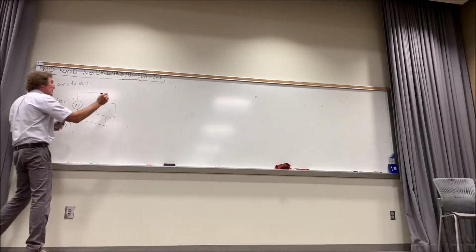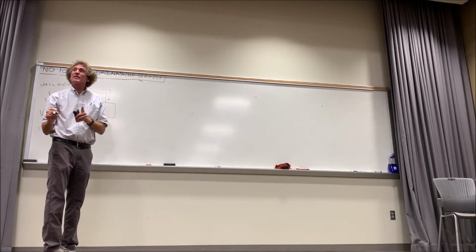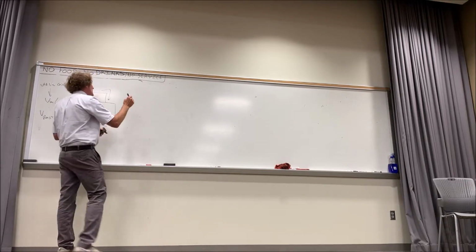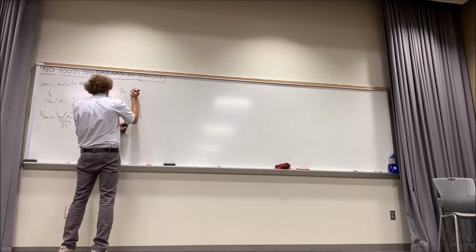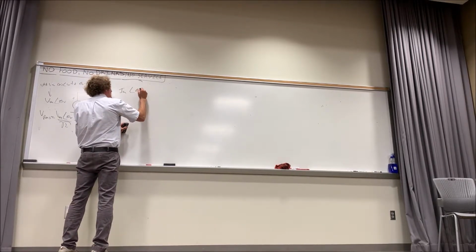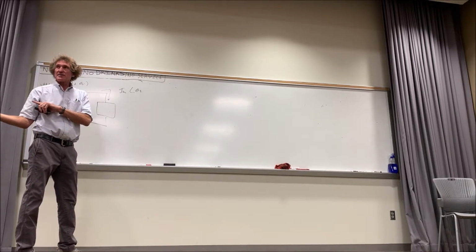Now here, there would be a current. This is going to be the peak current flowing in the phasor domain, not time domain. That peak current would be some Im, right? And here, it would be at some angle theta I. Follow me? Magnitude and angle are the only things you care about if it's steady state. You get rid of the omega business, all right?